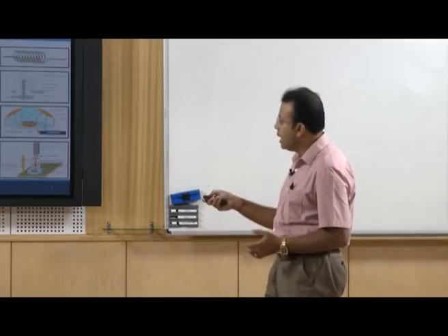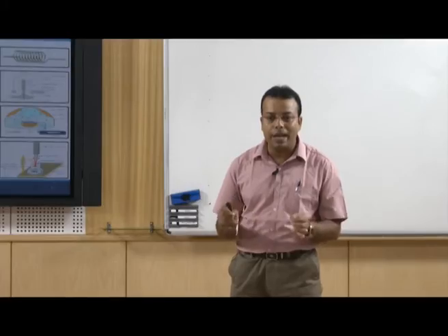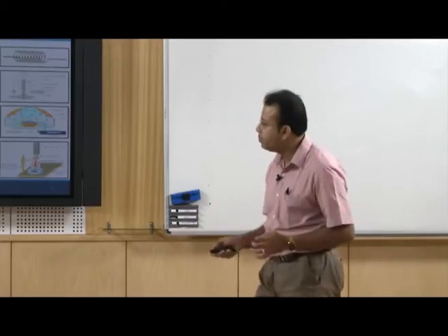The next one is called inductive heating. So, the evaporated material is heated by a high or low frequency induction method. Here we are going to use induction methods, that is why this technique is known as inductive heating. The evaporated material has to be conductive. So, it is not possible to use any kind of insulating material.